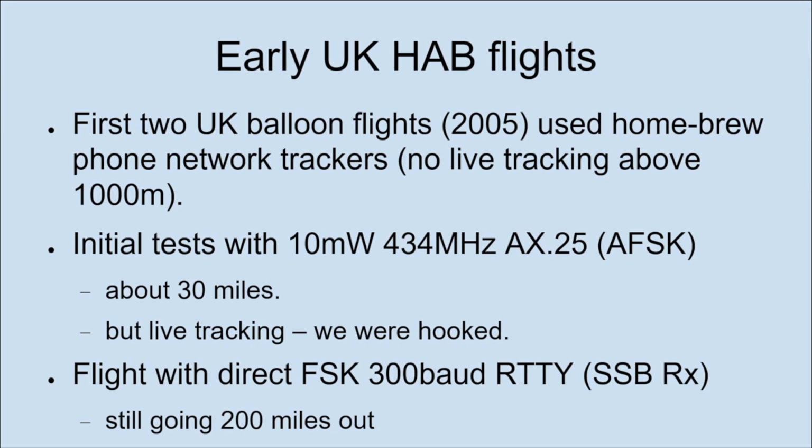So we looked at an alternative and found that 300 baud RTTY direct FSK was pretty good. We had a couple of balloons that disappeared out into the North Sea, and we were still hearing them 200 odd miles away. So we thought, yeah, that works for us. So it pretty much became a de facto standard pretty quickly.